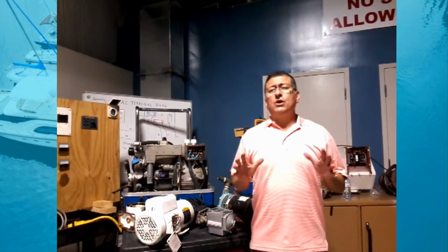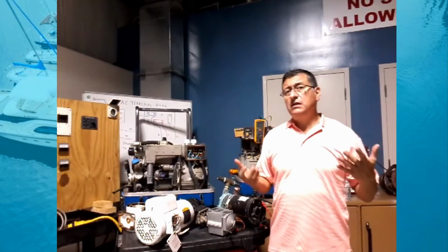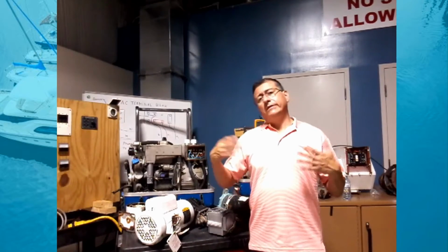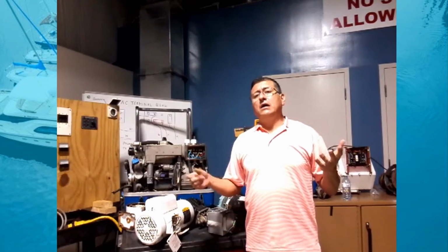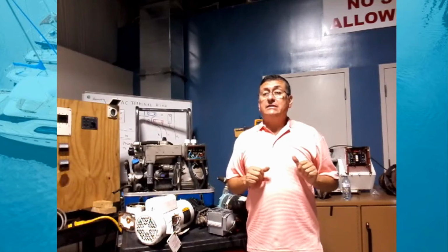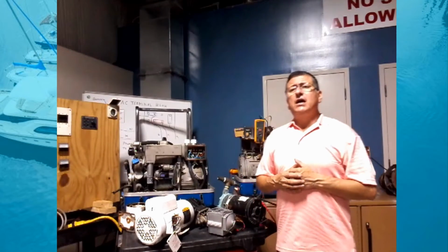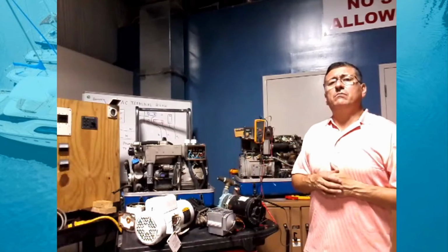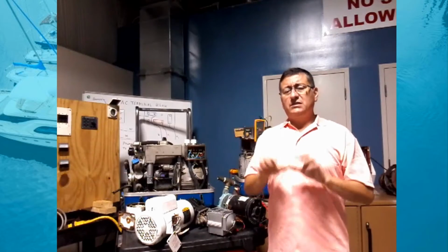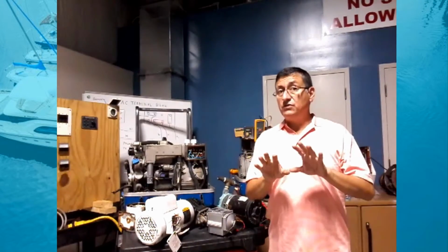In the previous episode, we talked about the frequency, and I explained the process to calibrate the frequency. If the frequency is too low, normally it's a mechanical problem related with fuel or gas. If the frequency is too high, normally it's a problem at the governor of the fuel injection pump. It's a mechanical problem on the engine. High RPMs, overspeed, is normally a problem on the governor of the fuel injection pump for diesel engines.